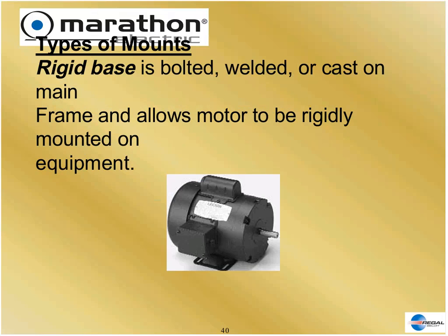Okay, now we have to bolt this motor down. We have to hold the motor in place for the customer to use it. So, several ways we do that. One of the most common is called a rigid base. Let me bring my motor back in here. The rigid base is that foot thing there with the holes in it that's welded, bolted, or cast into the frame. Therefore, it's called rigid. That's what you bolt the motor down, to a base plate, to a table, to the floor, wherever you need to, and then you come off the drive shaft over here to do the business end of your work.